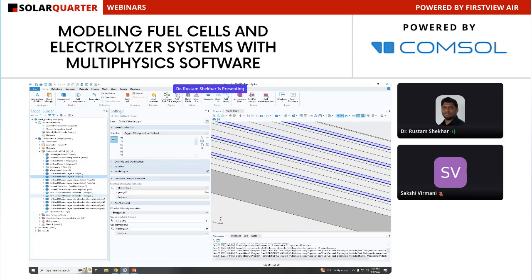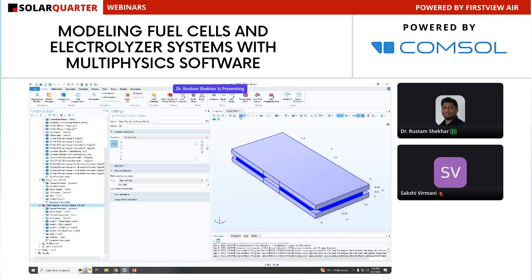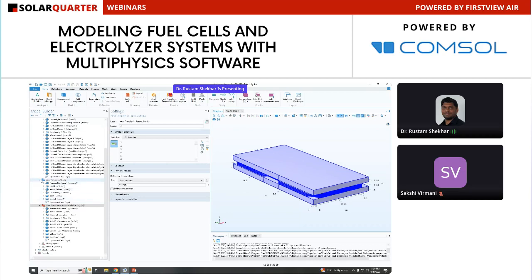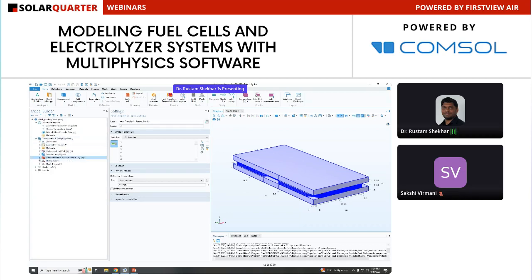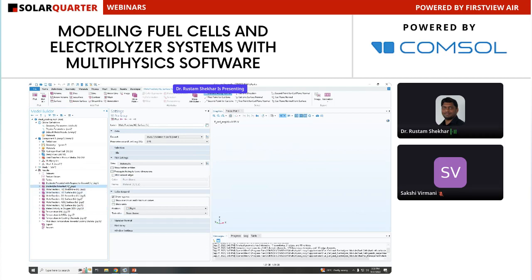The same level of details are available, but we are going into the detailing of those kinds of stack level modeling. For the flow, we are solving Darcy's law, and for the heat transfer, again we are solving heat transfer in the entire setup. So this way, you can solve for this and again obtain the same profiles like polarization curves and the temperature, phase profile, and the electrolyte potentials. All those details again you can plot and visualize. You can perform the stationary or the time dependent studies in detail.